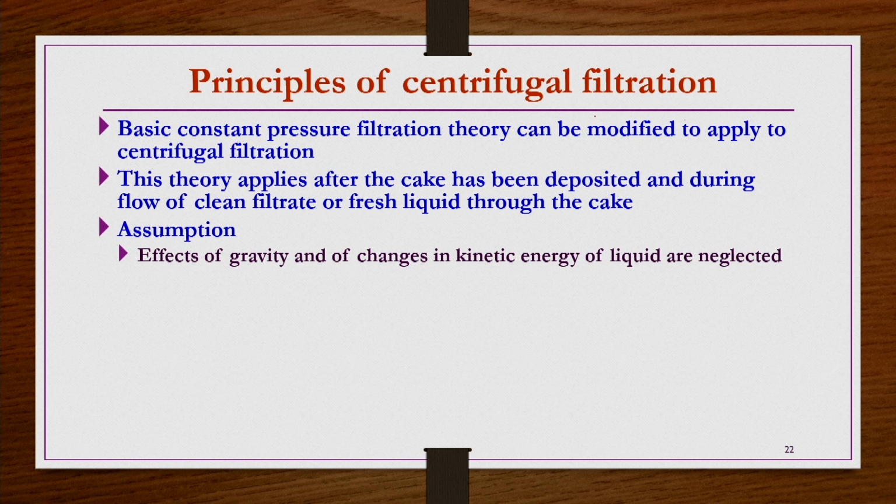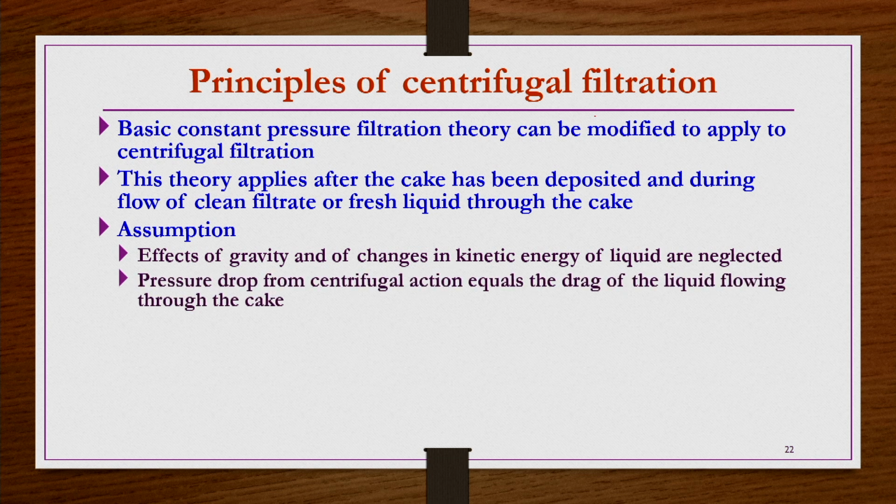Effects of gravity and of changes in kinetic energy of liquid are neglected compared to the centrifugal forces. These quantities, gravitational force and kinetic energy, are very small. That is what it means. And the pressure drop from centrifugal action equals the drag of the liquid flowing through the cake, same as a packed bed case.